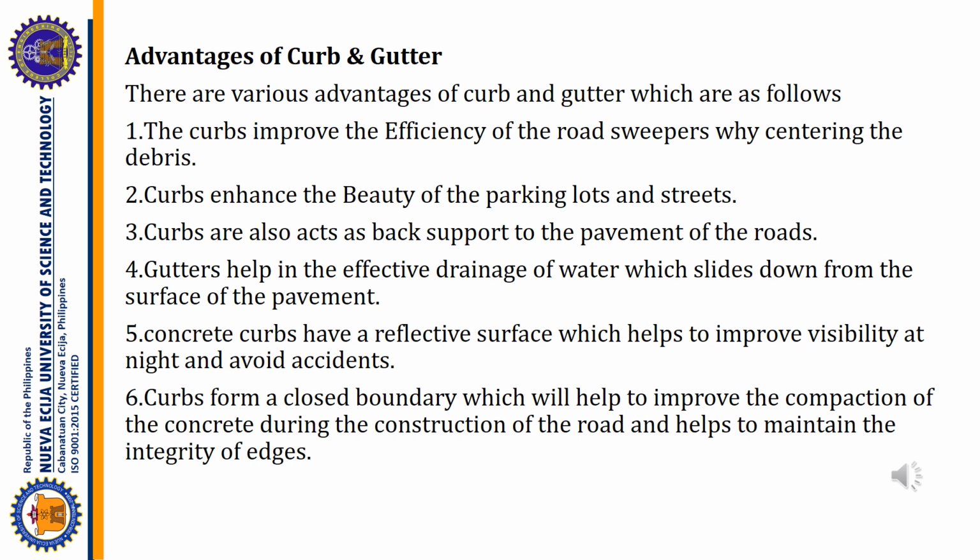So here are the advantages of the curb and gutter. The curb improves the efficiency of the road and sweepers while centering the debris. Curbs enhance the beauty of the parking lots and streets. Third, curbs also act as back support to the pavement of the roads. Fourth, gutters help in the effective drainage of water which slides down from the surface of the pavement. Fifth, concrete curbs have a reflective surface which helps to improve visibility at night and avoid accidents.